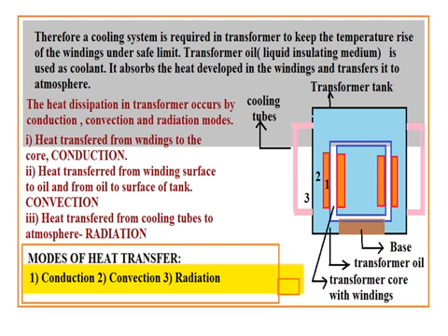Then one simple diagram is shown here. So it is the transformer tank. It is filled with the transformer oil, in which the whole transformer assembly is kept. Then on the side a number of cooling tubes are provided. Hence, the amount of heat developed inside the windings should be transferred. Heat dissipation takes place by all three modes, that is conduction process, convection process